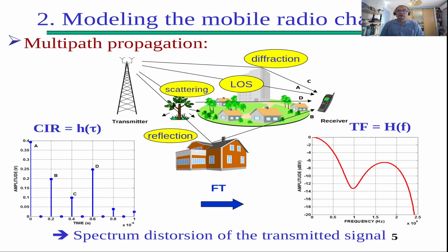So if you look at what happens at the receiver, I just have to remind you that it's a digital receiver, so you find a sum of impulses, Dirac delta functions, representing the different paths that come from the environment. They are separated by different values of tau, tau being the delay representing the length of the path that the path travels.